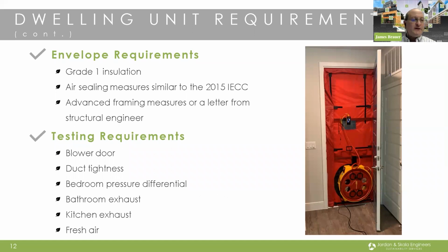Lastly, within the dwelling units, we thought we would touch again upon and remind you of some of the things we've mentioned before about the performance testing that's needed. The blower door test tests the air infiltration, or how tight your dwelling unit is, making sure that the air that has been paid to heat or cool doesn't easily bypass and leave the dwelling unit.